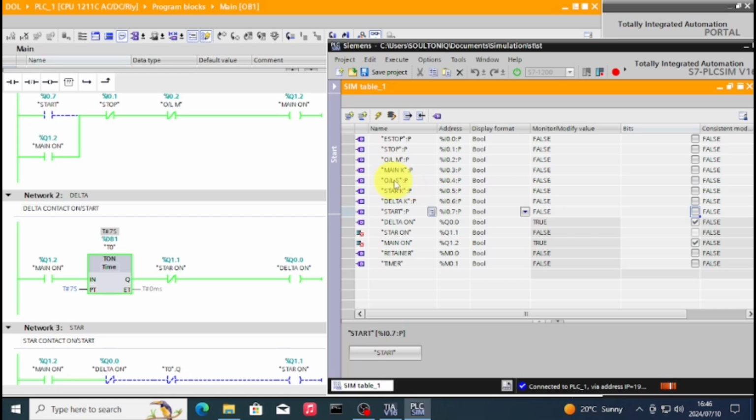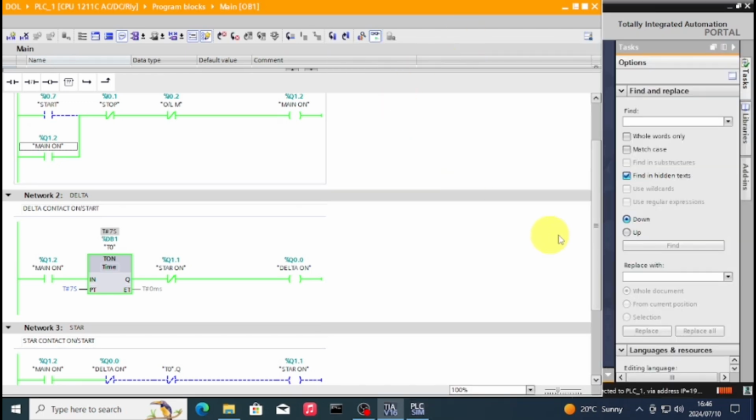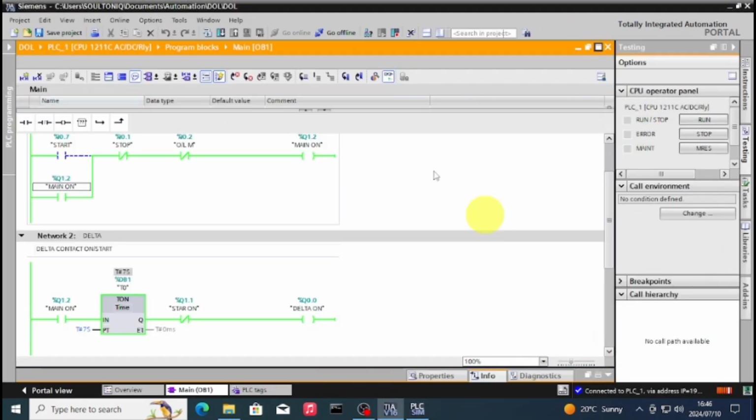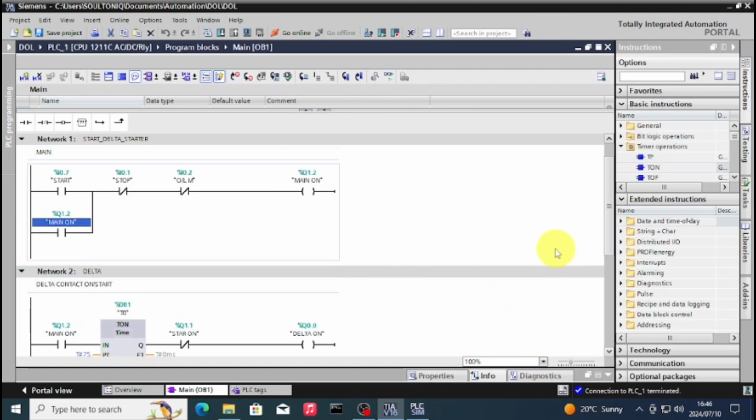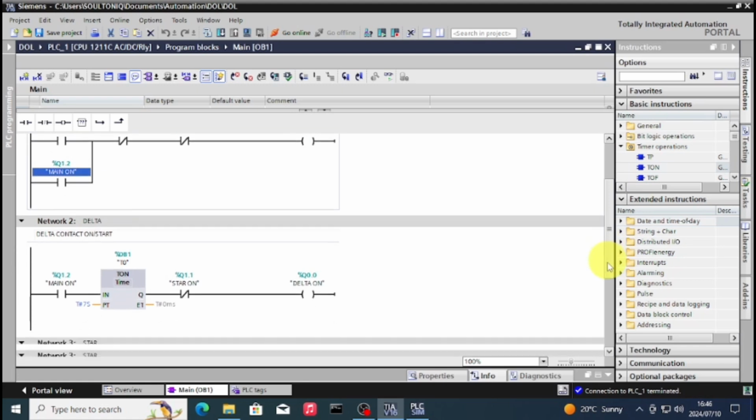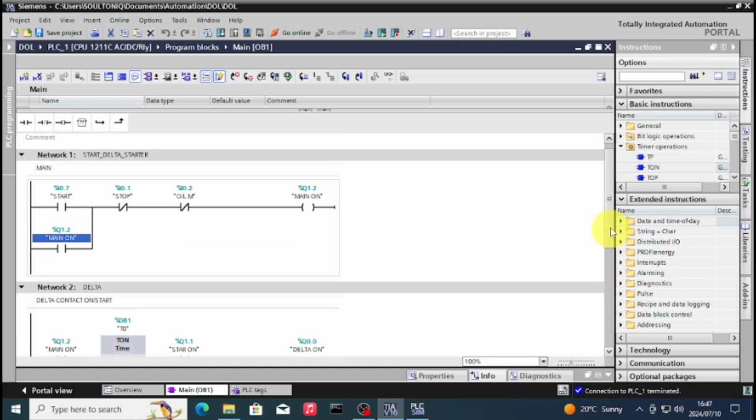The star delta starter method is preferred because it uses less space in your panel, and it is inexpensive, and it has no limitation, which means it's a continuous run on your motor. And it also can handle the unbalanced load and uses almost 1/3 current on a startup.